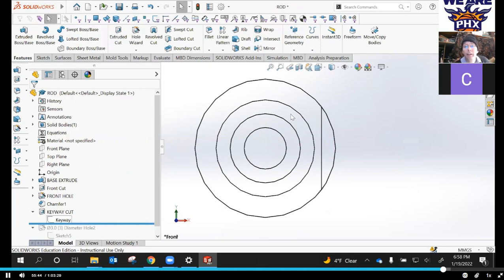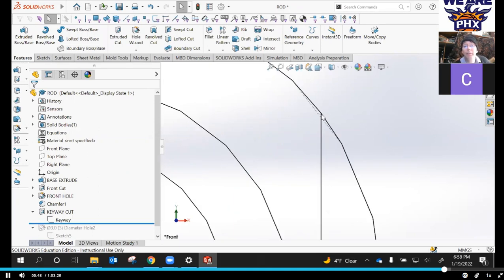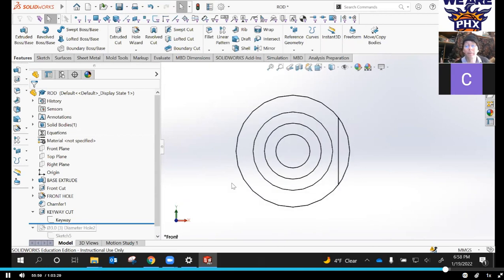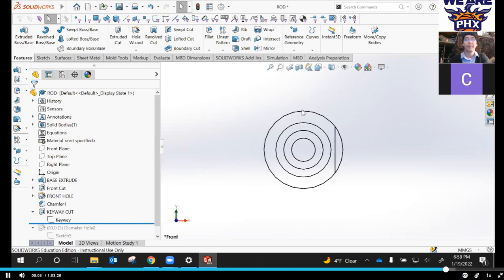That's okay now. I think it was probably extending past the edge. So if I grabbed it and brought it down and it connected to the end of this radius, now it's good. So the caution symbols have gone away and we're happy. We have a good part.